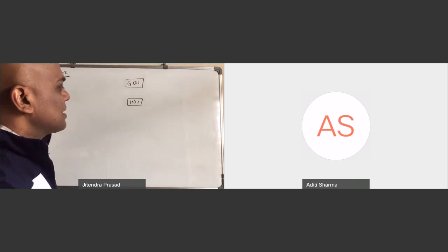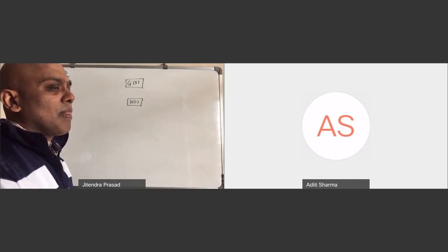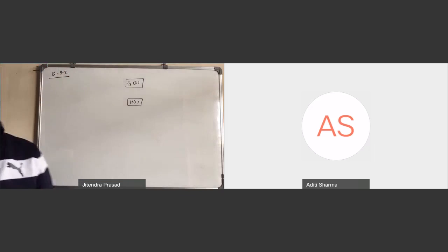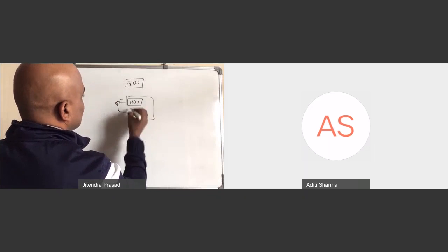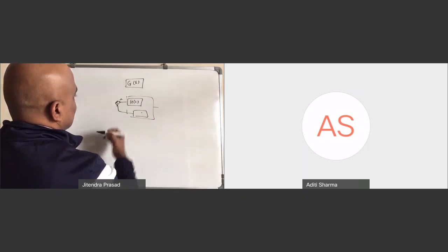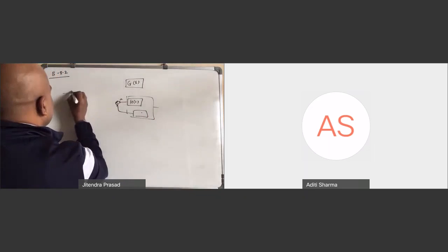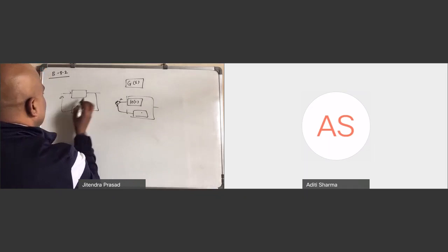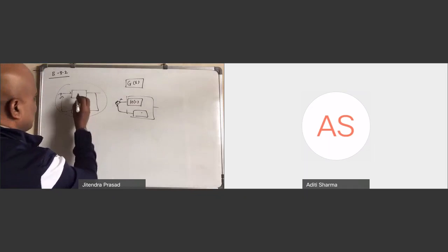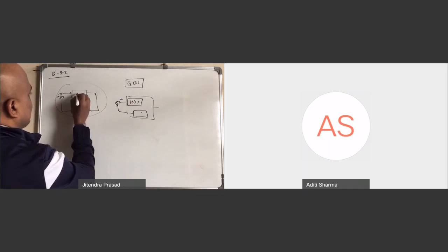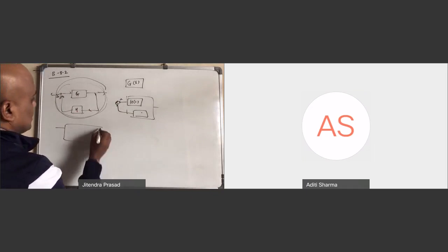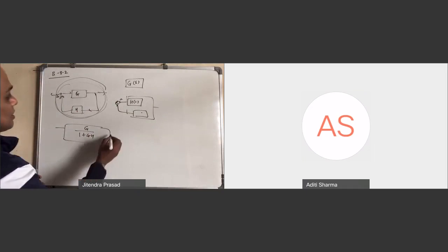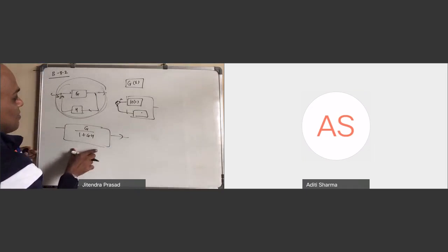But in any case, with this kind of thing, you can think in terms of combining them one at a time. For example, if there is a plus here and another plus here, you write them together rather than separately. Also, if it goes like this, with a minus here, and it's G and this is H, you know that between this point and this point you can simplify it as G over 1 plus GH. So the whole loop will be equal to this.